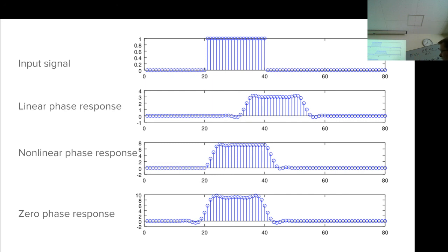If you have a nonlinear phase response, you would start seeing something like that, which you have probably seen on, say, analog filters of second order or higher. When you hit a system with a step, it goes up and then it has some ringing. Same way, when you go down, it goes down and then some ringing. So this is asymmetric behavior.